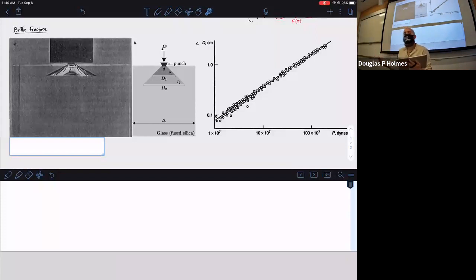Linear elasticity is a linear system of equations, unlike Navier-Stokes, which has nonlinear terms. The linearized form of elastic behavior predicts that you can increase the load indefinitely, and you'll just indefinitely increase the displacement, which we know is not true. If you bend something too much, it'll break. If you pull on something too much, it'll break. So it seems like that model would be insufficient to capture fracture.